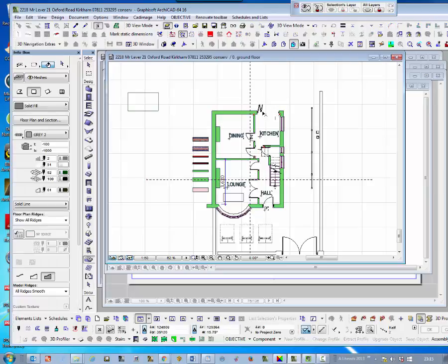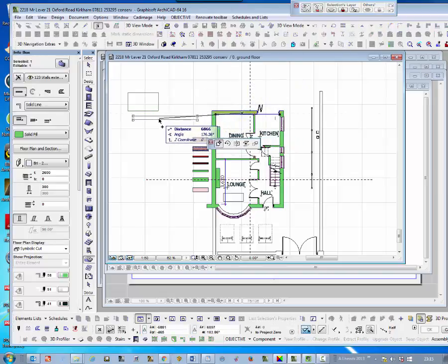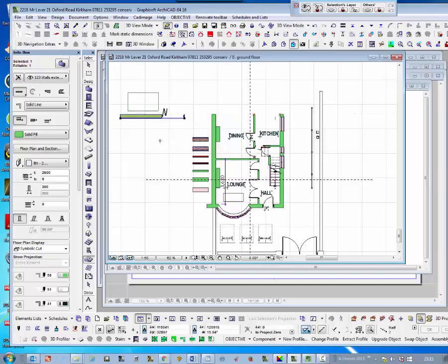Now in this case, that being a bifold door, we're not going to need that, but just in case we do, we can shift click the whole wall, which will contain the door, and if we press Ctrl and Shift and pull it to one side, if you see the plus as we're dragging it to one side, the plus means that we're actually taking a copy with it. So let's put that there. Oops. Ctrl Z, it's obviously done the wrong thing.